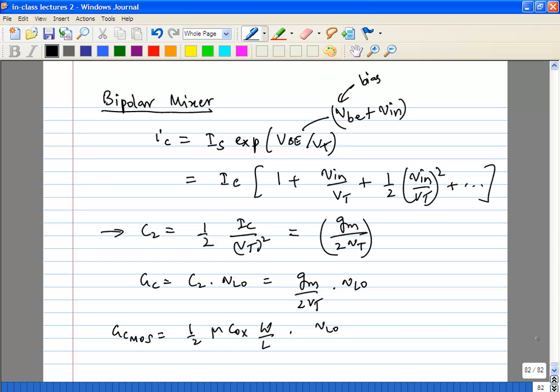No, you can, of course. You can always give it at the base. You have a separate bias current, so you have the bias voltage plus signal going in at the base, and a bias current source at the emitter. That is fine because it's an exponential rise. The extra bias voltage will fall across the current source, right? That is what we always do. So we are not controlling the bias VBE in any case here. We are controlling only Vn, which is being given as the small signal VBE across the bipolar transistor.